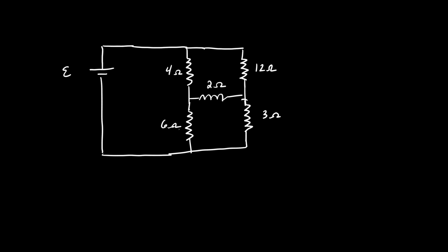Now, we don't do circuits like this. And this actually has a name. It's called a Wheatstone bridge. And I don't know how to spell it, but I'll say Wheatstone bridge. It actually has a use. It's for figuring out very sensitive resistances. Because there's a potential difference between these two sides, you can tune one of these resistors to reduce that potential difference down. And when you do, you can get highly accurate measurements for resistance. That's what a Wheatstone bridge is used for. But I just want you to be clear, there are circuits that don't have series and parallel, but we stick with the basics.